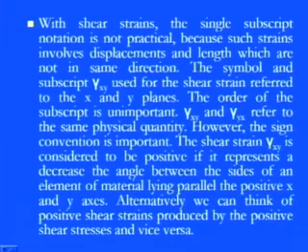The shear strain gamma xy is always considered to be positive if it represents a decrease in the angle between the sides of the element of material which are lying parallel to the positive x or y axis. That means if the angle is decreasing, we always consider the positive side. We can think of positive shear strain as produced by positive shear stress. And again, negative shear strain means there is an increase in the angle between the sides of the element of material which are lying parallel to the x or y direction.